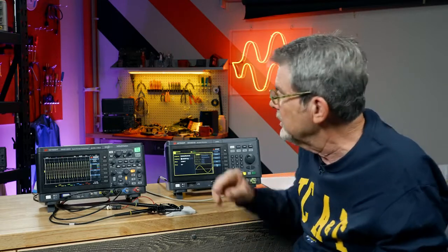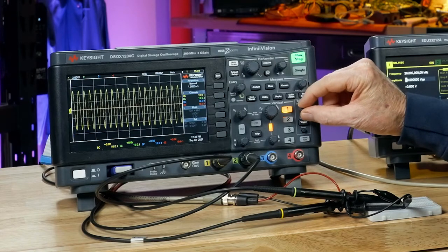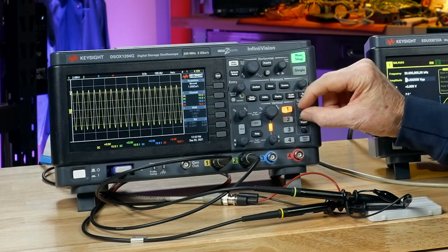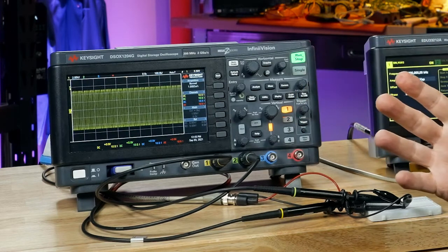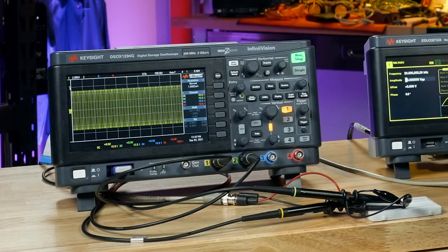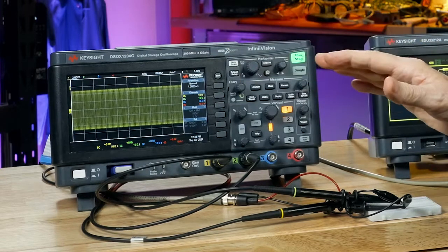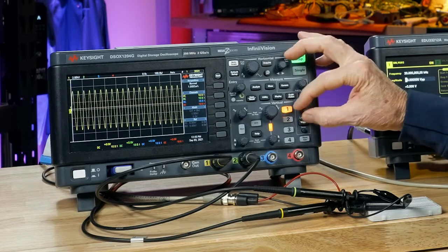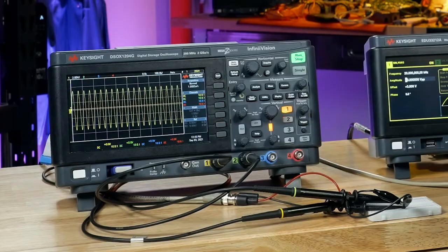The next step is to adjust the trigger level. Now triggering is really important, and we're going to get to that in a later lesson. So this is the trigger level. As soon as I rotate the knob, a horizontal line pops up and shows me where the level is. If I move it up above the waveform, the scope loses trigger. I haven't explained what that is yet, but all you see is a blur of signals. So for now, just set it about the middle of the waveform.